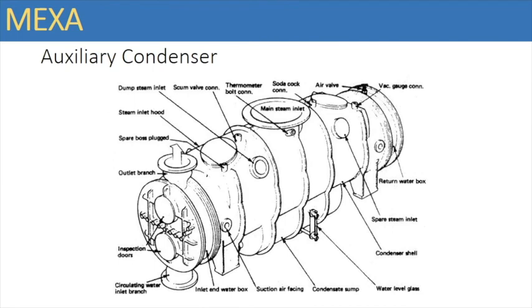In the feed system, the atmospheric condenser is the most prominent component which maintains the feed system in a loop, be it closed system or an open system. The condenser is nothing but a shell and tube heat exchanger which removes the latent heat from the exhaust steam so that it condenses and can be pumped back into the boiler. This condensing should be achieved with the minimum of undercooling, that is, reduction of condensate temperature below the steam temperature. This is achieved by seawater cooling by a two-pass flow in the tubes.